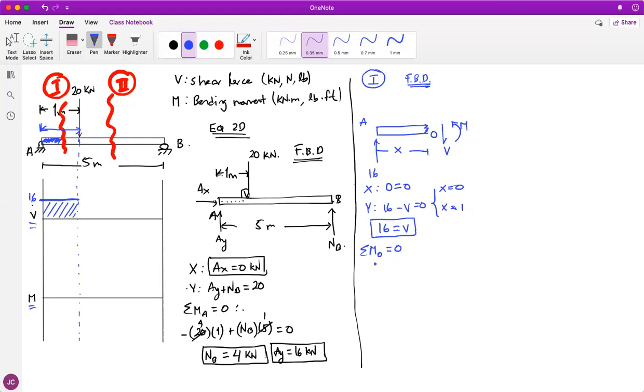And what we find over here is that, maybe you see it, 16 is not being applied at O. So I would see a 16 times X, because you need to walk X in order to find this 16. And it's going to be a minus according to your right-hand rule. And then what about B? Oh, nothing about B, just 0. Yeah, the moment produced by B at O is actually 0.